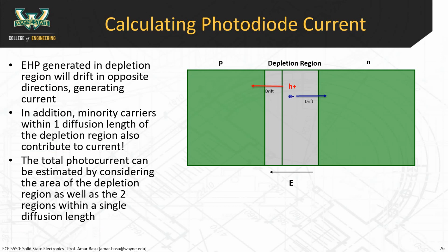So you can already realize why, in solar cells, you want to maximize the P and the N interface, the area that we were just talking about. Just having a bunch of P-type material is not going to do it, and just having a large P and large N-type material that has a linear junction like this, that's not going to do it. You want to maximize the interfacial area between the P and the N materials.